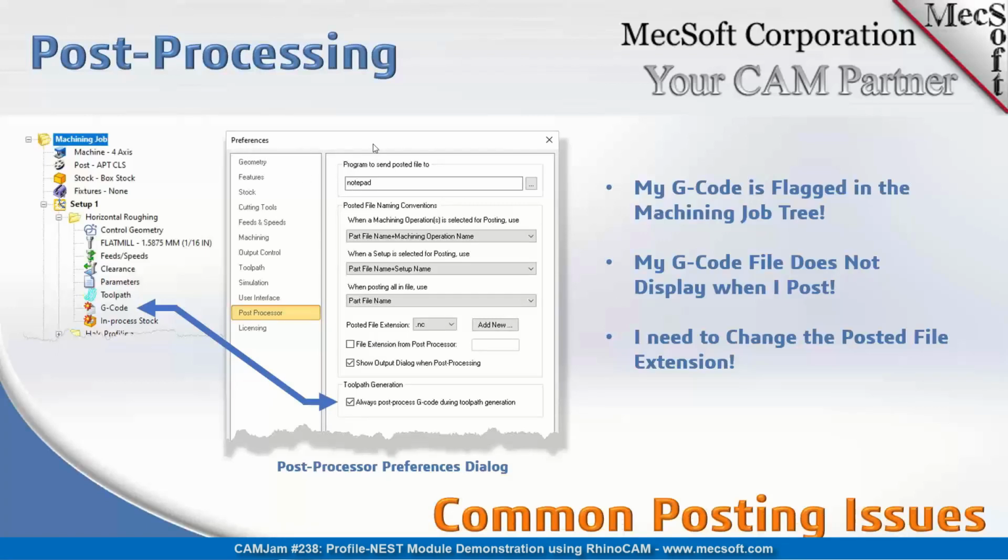Just go to the CAM preferences dialog, pick the add new button right here next to posted file extension. It'll pop up a little dialog. Enter your file extension .xxx, whatever your extension is, pick OK, and then it'll appear in this list of posted file extensions.